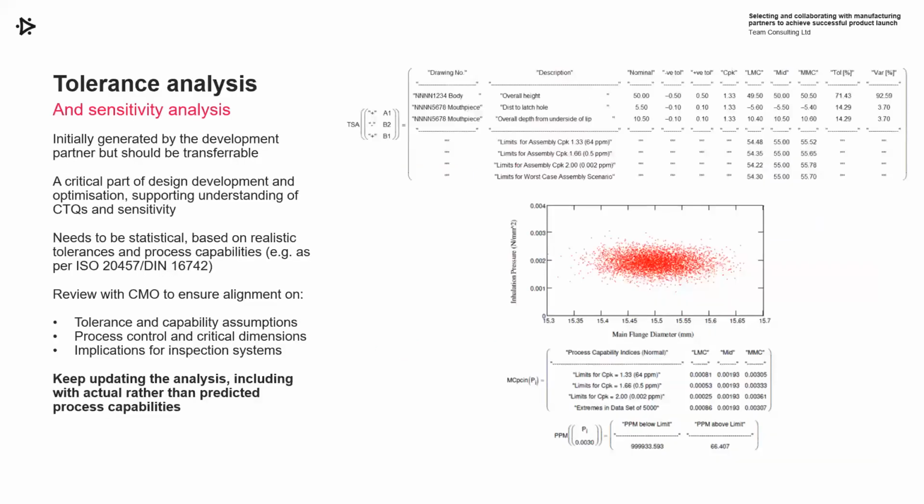Tolerance analysis, this is quite a specific one, but it's very important. It's really developing the full understanding of the design and how it works and how efficiently it can be put together. It's initially generated by the development partner, but it needs to be transferable. So think about when you're creating the tolerance analysis, develop it in a way that can be transferred as needed.